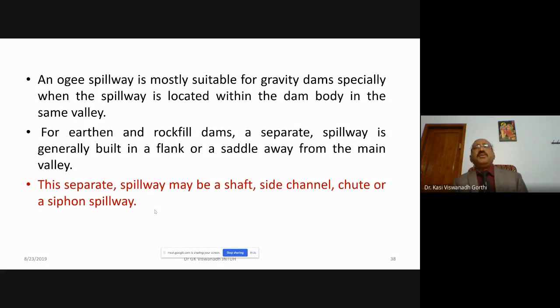Then types of spillways on different grounds: normal spillway, design spillway, emergency spillway, and then, depending on the method used with respect to the location, the spillways are classified. We have seen the straight drop spillway and secondly the ogee shaped spillway. These are the two spillways that we have discussed in today's session. Ogee shaped spillway is the most commonly used spillway, and to arrive at the profile for the ogee shape, the downstream and the upstream profile with respect to the origin C, which is the crest of the spillway, we saw the WES profile and worked out a